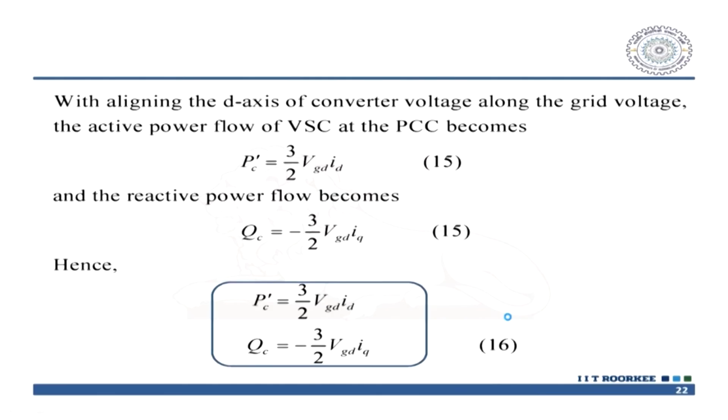So, going back to the discussions again. This is the way the PLL works, but it will work only when your voltage is healthy. If there is an issue with unbalance, you get a positive as well as a negative sequence component of the voltage, then you require to do something else to estimate the PLL. If time permits, we will discuss those PLLs in detail, but let us take an elementary example of it and proceed.